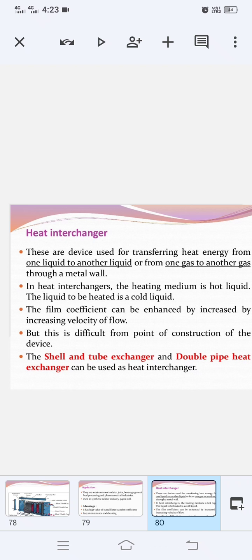First one is the liquid to liquid interchanger. The basic construction and working of any heat transfer equipment more or less remains the same, only a few modifications are included. The construction of a liquid to liquid interchanger normally has tube sheets, spacer rods and baffles, which are assembled first, and then tubes are installed in between them.